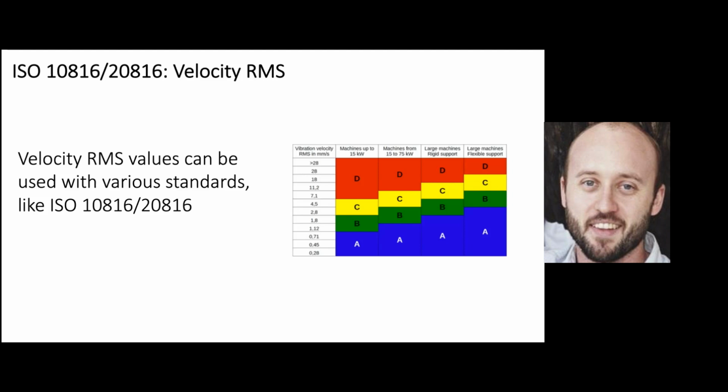And it's not always exactly perfect. Remember, back to our discussion of false positives and false negatives in session 1, this approach is a threshold approach. That false positive, false negative trade-off is applicable in this case. So it's not a sure-proof way. However, this is a really, really good starting point for doing vibration-based condition monitoring as sort of a spot check.